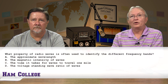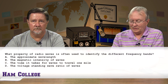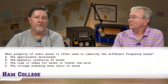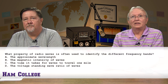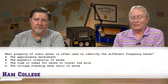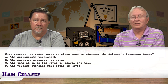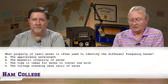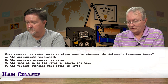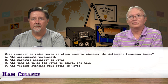Well, I don't know of a VSWR, voltage standing wave ratio, as being used to identify one of the bands on ham radio. The time it takes for the waves to travel 1 mile, no, we know that the speed of the waves doesn't really change with frequency. B, the magnetic intensity of the wave, that just wouldn't really have anything to do with it. If it had anything to do with anything, it'd be more about the strength of a wave rather than the frequency of it. So A, the approximate wavelength.